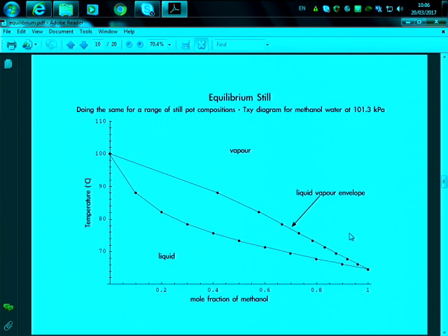So let's say that we evaporate at 80. Okay? We want to know where the thing will stop, at equilibrium. We have already discussed that things stop at equilibrium. So at equilibrium, when you have the separation process occurring, you will have this amount of vapor, and in the vapor phase you will have these small fractions of methanol and whatever's left of water. And in the liquid, what is staying in the liquid and not evaporating will be this amount of methanol and whatever else is water.